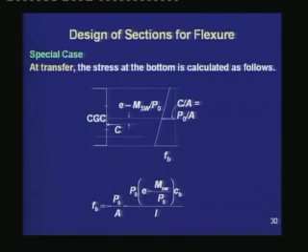Thus, here instead of calculating the stress from the similarity of the triangles, we are calculating the stress from the basic concept of stresses, that it consists of a uniform stress block and a varying stress block due to the eccentricity of C.